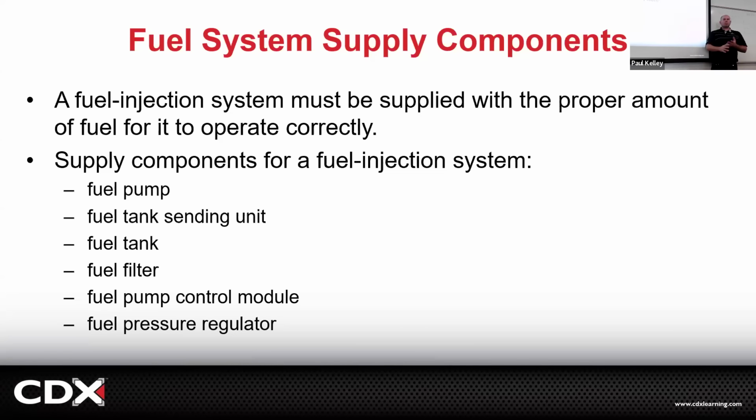The only reason we'd need a fuel pump control module is if we're going to try to vary the output of the pump, right? Back in the day, we just sent the pump full, everything you got, all the time. That was one way to do it, but it was kind of hard on the pump. Now, if it's at idle, we can have a fuel pump control module slow the pump down and say, hey, you don't need to pump all crazy, it's just at idle, chill. But we need a computer to control that. That's what the fuel pump control module is.